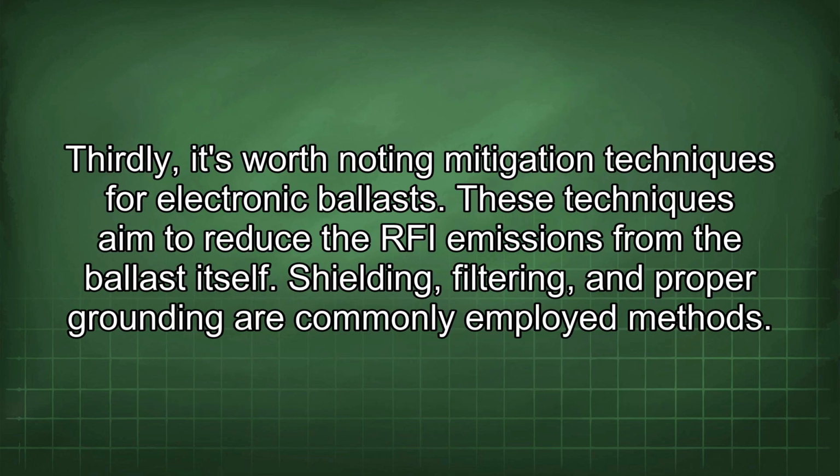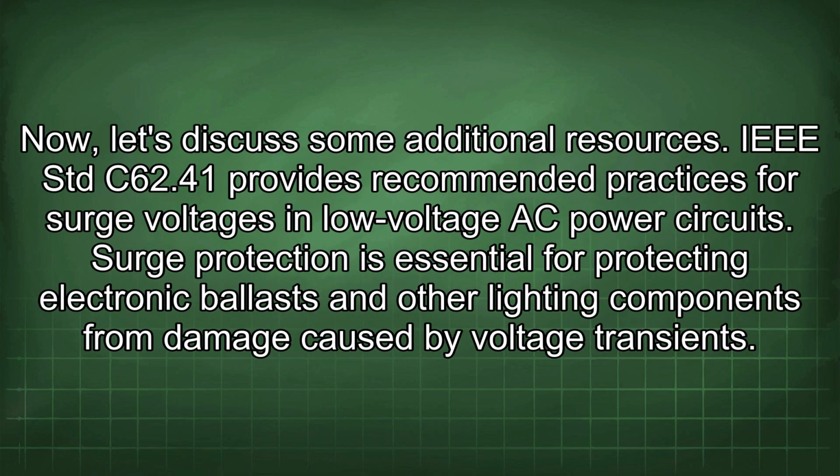Thirdly, it's worth noting mitigation techniques for electronic ballasts. These techniques aim to reduce the RFI emissions from the ballast itself. Shielding, filtering, and proper grounding are commonly employed methods. Now, let's discuss some additional resources.